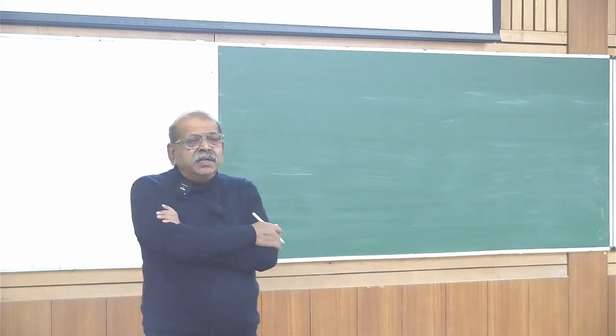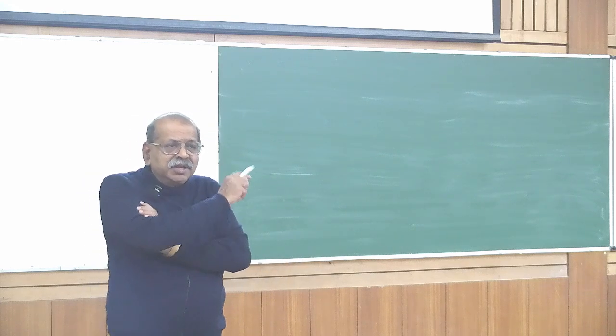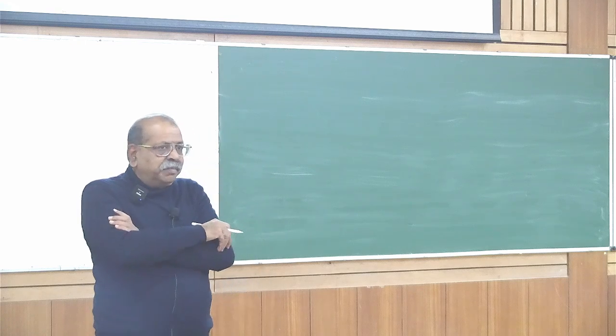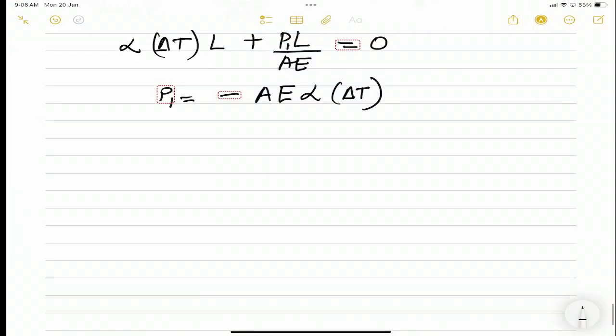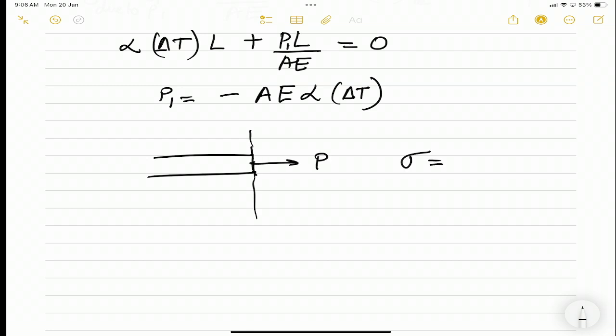Does this mean that there are no shear stresses in this whole bar? Now, this is the face which I have looked at, and here if the force is P, you have sigma is equal to P upon A. And actually on this face, the shear stress is 0.